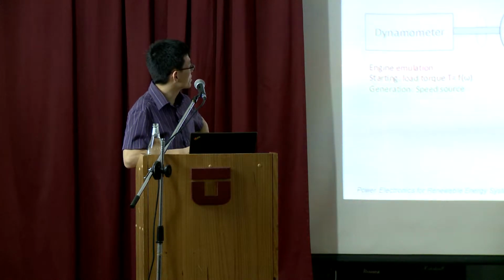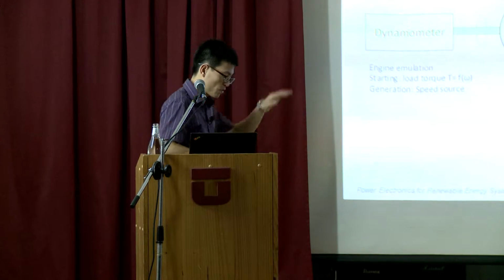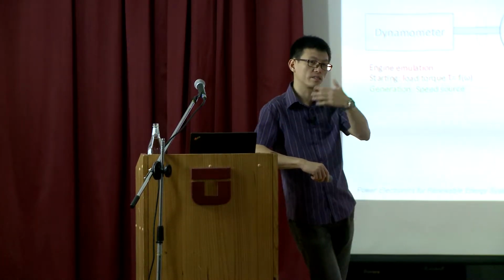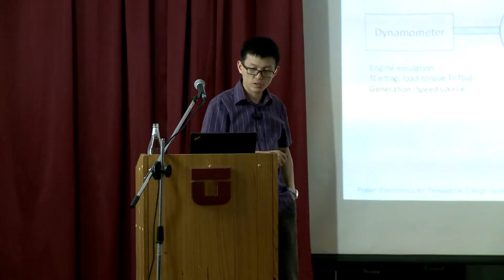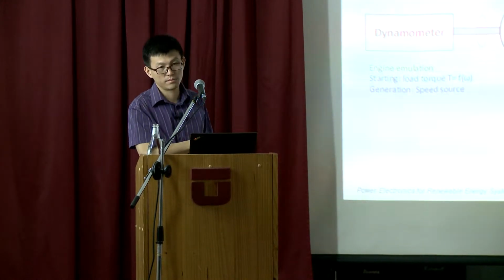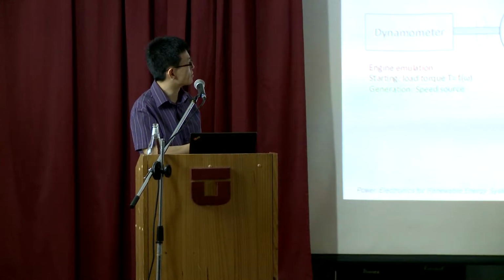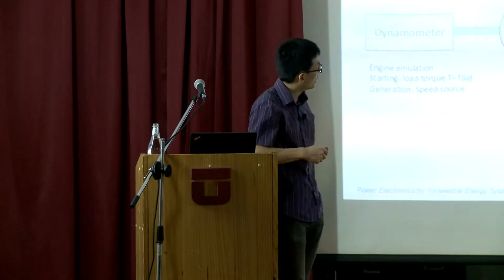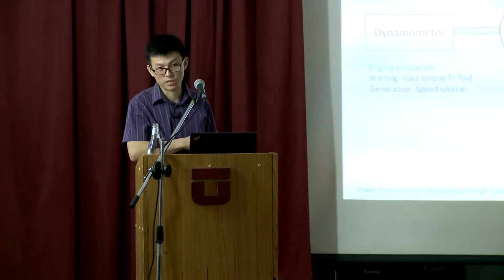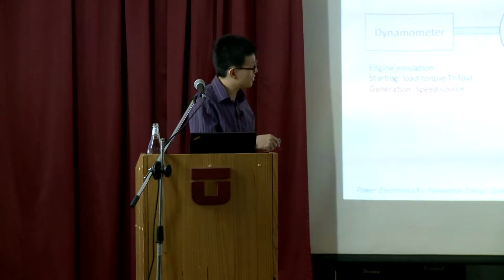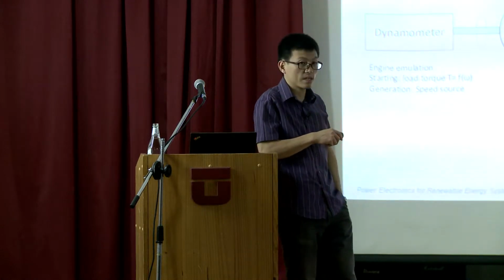This is the machine, and this is the power converter, as I talked about, and this is the GSS. It's a 4-quadrant DC power supply, so it can be used as a load and as a source at the same time. In motor mode, when this machine is a motor, the power transfers from the DC source to the machine. In generation mode, the prime mover drives the generator and supplies power to the load, the GSS. And then we can change the voltage on the GSS.